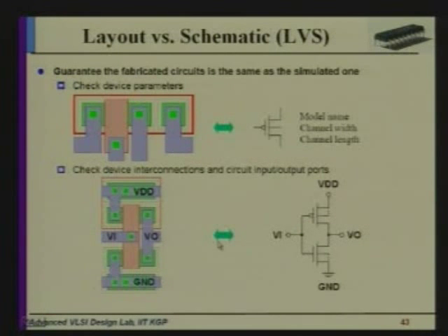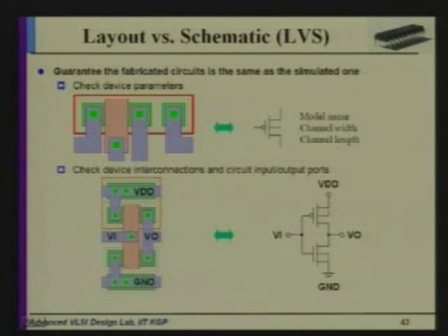And this is the layout. What does LVS mean? Layout versus schematic. Whatever you have simulated and whatever you have drawn, both should be the same, right? This check will perfectly match that one. It will compare the pins, the resistance width, the MOS width, MOS length, everything. It will also check whether the connectivity is proper or not.